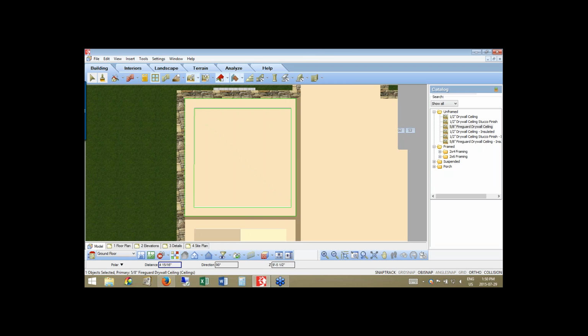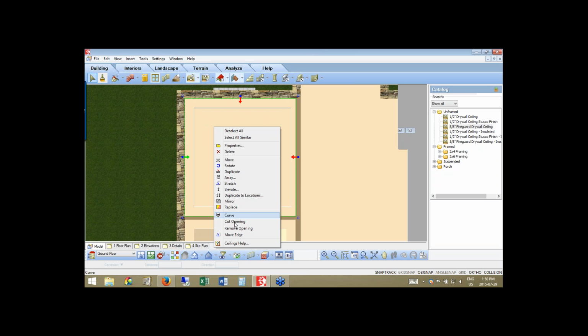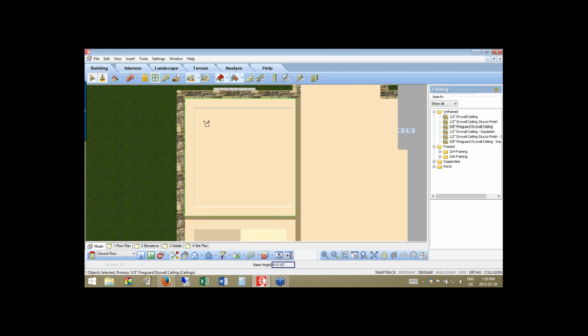Okay. Now that hole, right-click, I'm just going to hit cancel there for a second. That hole can be from any point. So if I wanted to sketch out a point here, I can type in dimensions. I can say I want to go over exactly 7 feet, I want to come down exactly 7 feet, and it's just a 7-foot by 7-foot square hole in the middle there. I can type in the distances too. I don't have to pick from points. Then I right-click and I tell it I'm finished.